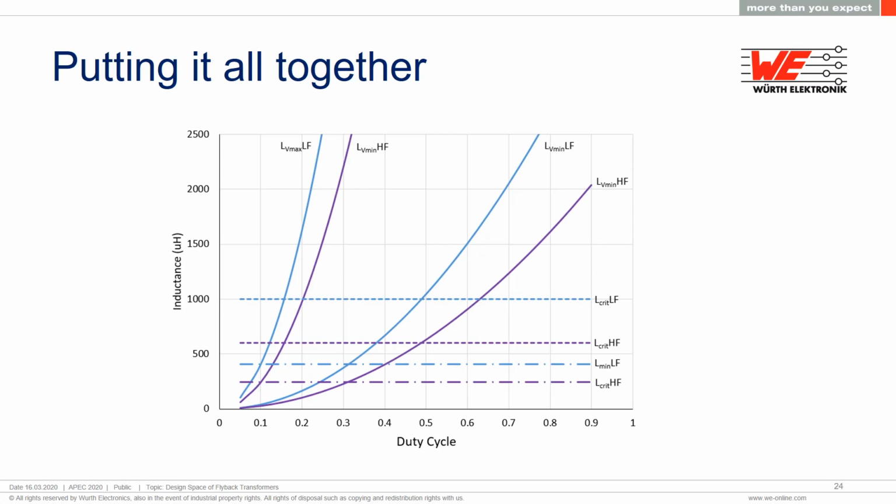In this slide, I've reproduced the same calculations, but I've used a higher frequency so you can see the effect of frequency tolerance. It could be as simple as the tolerance of the IC's fixed frequency, which might be 5%, or it could be a function of the external components that you use to set your frequency, or it could be your operating range for a variable frequency topology.